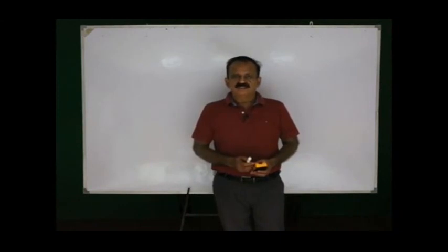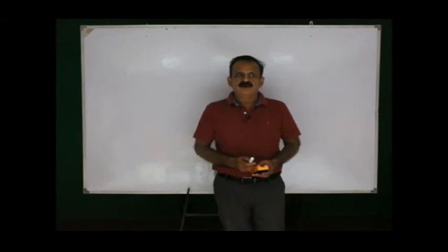The topic of discussion of today's lecture are encoder and decoder. Both encoder and decoder are combinational circuits. Combinational circuit means the value of output depends upon the current input values. It does not depend upon previous output or previous values. That is why no memory is involved in these circuits.